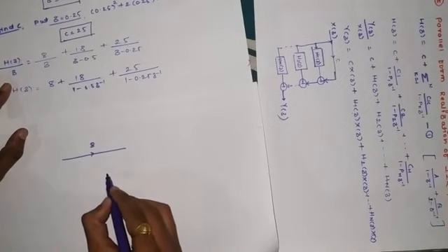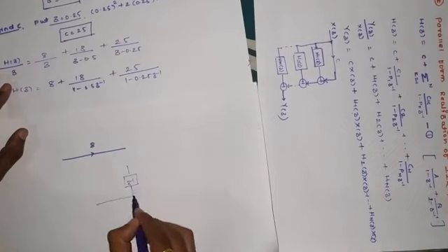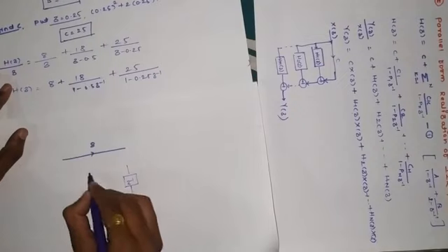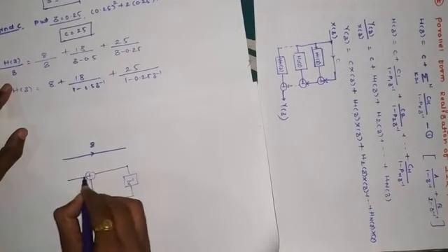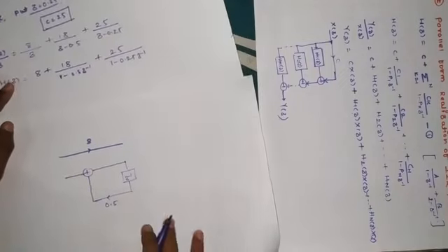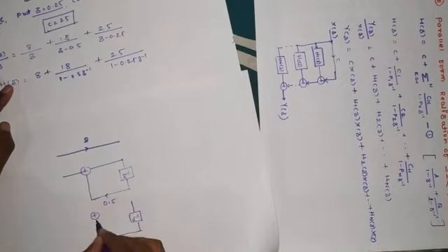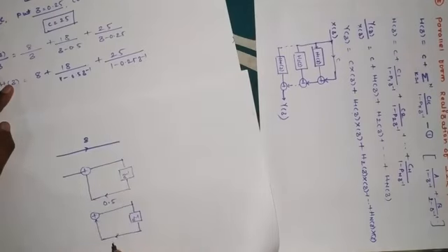So we need one delay element here. I am taking this as z inverse. Now this is multiplied with minus 0.5, so this becomes 0.5, that is plus. Only one adder is required, so we place one adder here. This is our H1 of z. Next, coming to H2 of z, again we need one delay element. So this is z inverse, and one adder is placed along with this. Now this is multiplied with minus 0.25, so it becomes plus 0.25, and this is the term.